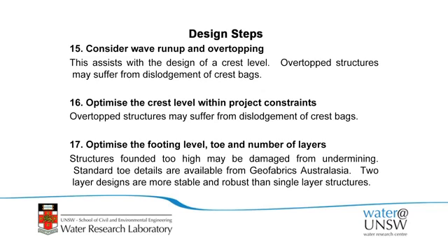I mentioned the toe level or the footing level. If it's put too high, obviously if you put your structure at about +2 AHD and the storm comes, scours it to -1, your whole structure is probably going to fall into a hole as well. So be careful about not undermining it. Even if your toe is at -1, which is the general rule of thumb, there are some good toe details that Geofabrics Australasia have to allow for scour. If it happens to scour to -2 or a little bit more than you designed for, you can still have a good toe design that allows it to collapse in the hole and not collapse your whole structure.